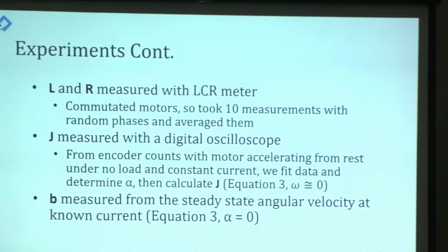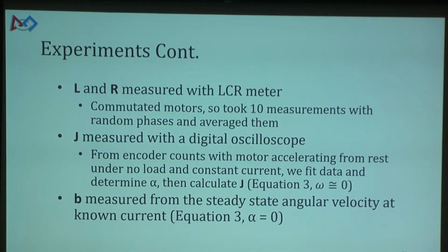And last but not least, we have B. For this test, we give a constant current to the motor, and then we let it reach its maximum velocity so that the acceleration is 0. To reduce this data, we use known values of KE, because we don't trust the values for KT very much, and we will get into this more later. J and B should be close enough, because J and B aren't that significant in terms of tuning PID algorithms.